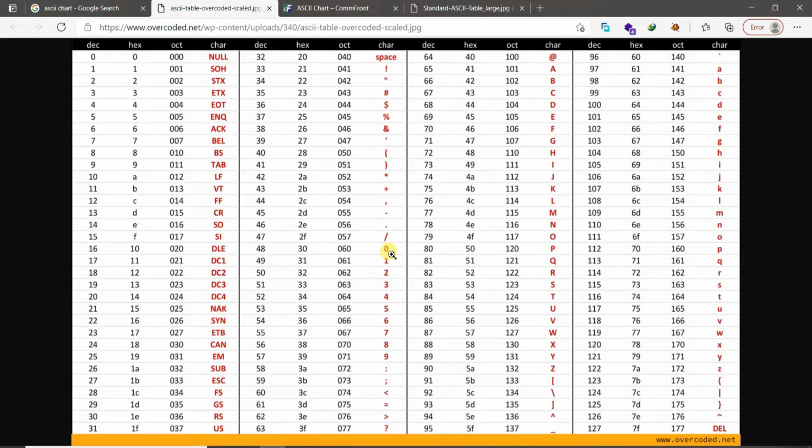The same thing is being done so far using the printf function. Why do we need to do %d in printf? That is because we are formatting the integer to be printed in its text format. So the printf function is doing the conversion from integer to ASCII for you. The problem with embedded systems comes because we don't have the printf function in embedded systems. So what we need to do is manually convert our numbers into their respective text representation.